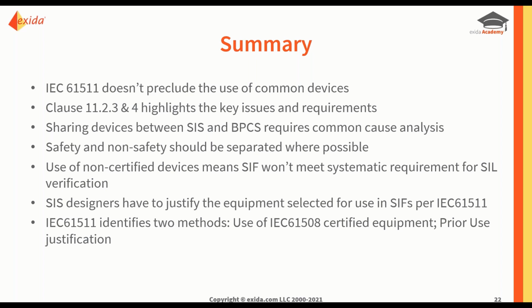General rule of thumb, safety and non-safety should be separated where possible, because otherwise you have to treat it as safety. And what I usually tell the classes is, if you've got some control functions that are not safety related, then if they don't need to be in the SIS, get them out of the SIS. If you use non-certified devices, then you're not going to meet the systematic requirement for SIL verification.